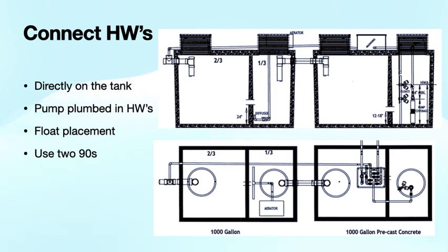A little bit of the guts inside of the tank. We have here, again, provided in the same kit, a half-horse turbine pump, and that's going to be the same pump for all these residential systems, and it's going to have an adapter to pare down where it's being connected to 1-inch PVC. The goal was to have everything so that you can use just 1-inch PVC. So you just need that one size of pipe, and it's a pretty typical size of pipe, and that's going to go directly into the headworks out of the riser here.